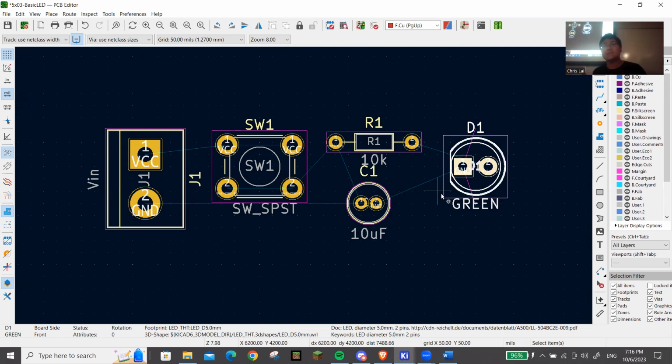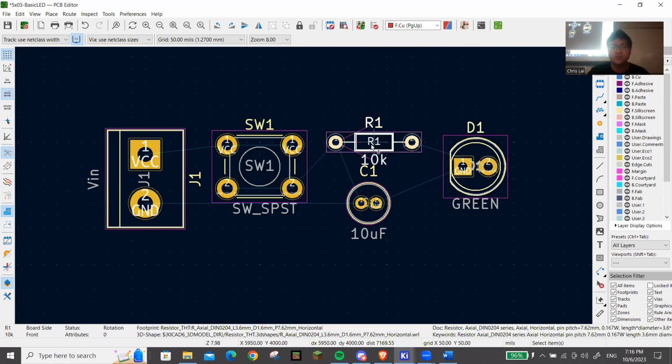Another good rule of PCB design is you want to try to get the smallest PCB possible. You don't want to waste any space. Now that's hypocritical of me to say because a lot of Blinky learners actually do waste space, but that's different. If you want a functional PCB to use in your robot, you want to make sure you have the smallest amount of space possible while giving each component room to breathe. Because if you put each component too close to each other, what can happen is when they're manufacturing, the components will short each other out. So there's a manufacturing error. So always Goldilocks zone, make sure each component has enough room to breathe.